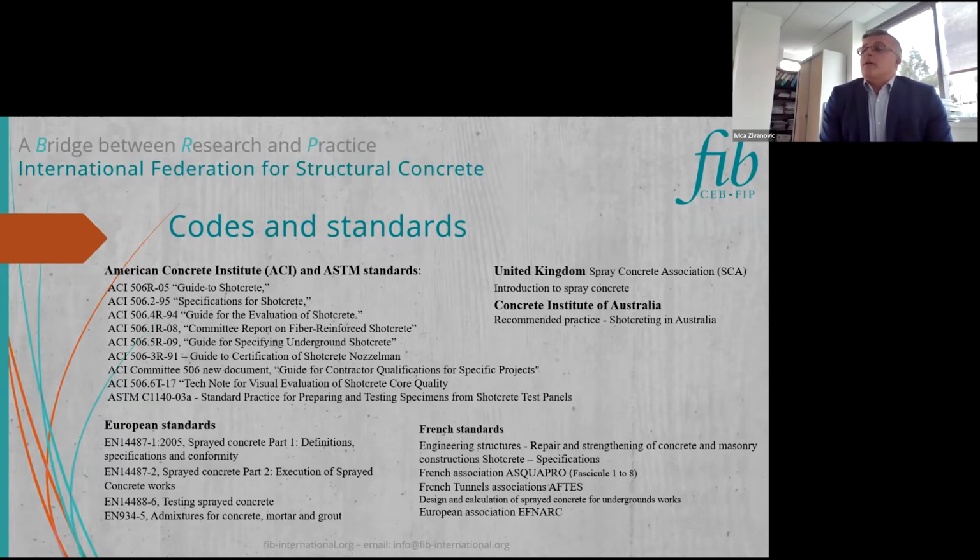European standards are also covering all the sprayed shotcrete definition, specification, and compliance, including in part 2 the execution of work itself, the testing on the constituents, and specification in terms of admixtures for concrete, mortar, and grout. And of course, there are typically standards per country, as you can see in an example related to France.